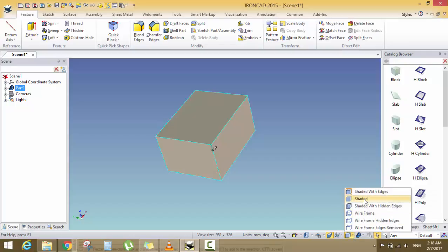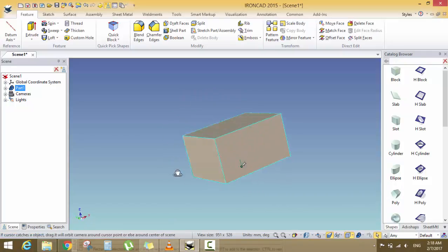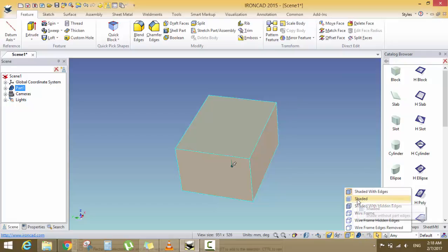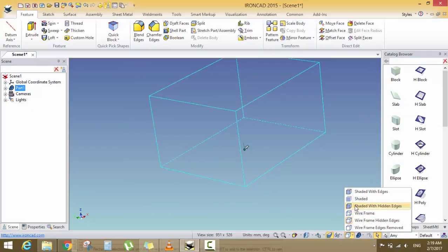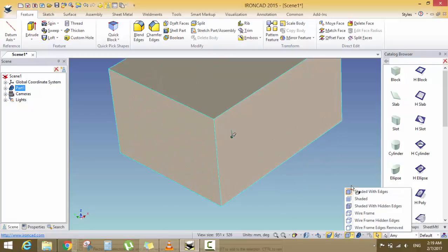This shows your view. For example, in the current view, you can see the main 3D model and the outline lines, or the outer lines of the 3D model. Another choice can be shaded. Wireframe, for example, you can create wireframe, or you can create wireframe and the hidden lines will be dashed like this, or you can make it... we work with a standard choice which is shaded with edges.